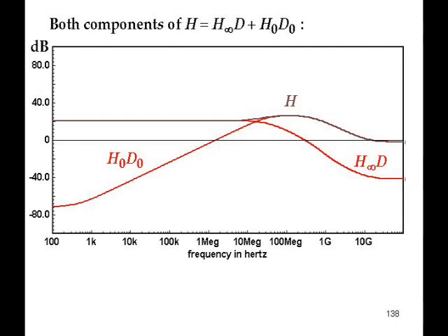The direct forward transmission through the feedback path in the wrong direction dominates the result at the higher frequencies and makes the H itself have a peak. This means that if you did a step function response, you don't get a huge ringing overshoot because the phase margin is fine. In fact, you get a huge undershoot. But we don't need to go into that. The point I want to make here is the direct forward transmission term, a non-ideality, dominates the result.